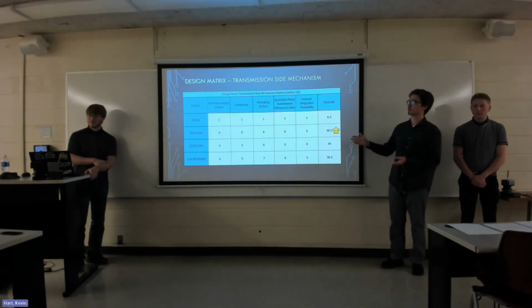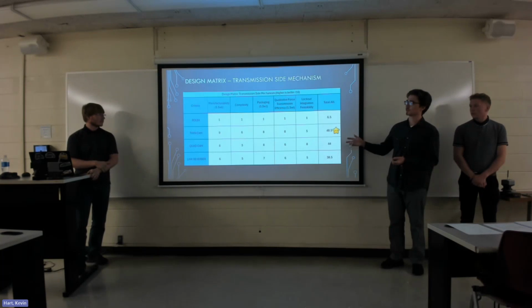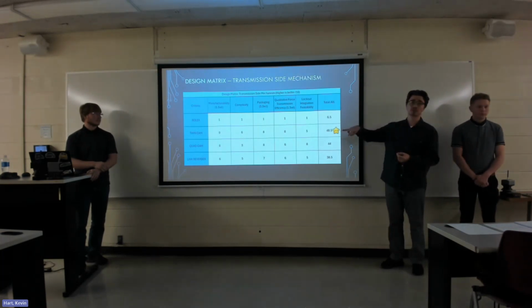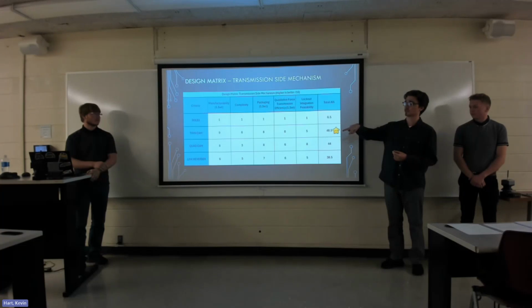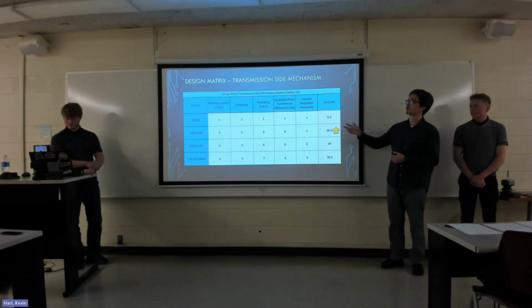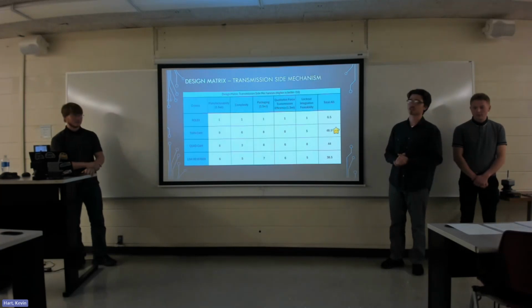Ultimately, we went with the twin cam setup because we believed that we could switch two of the quad cam mechanisms to simple reversers. Some of the criteria that were most important for us were manufacturability, packaging, and qualitative force transmission efficiency.